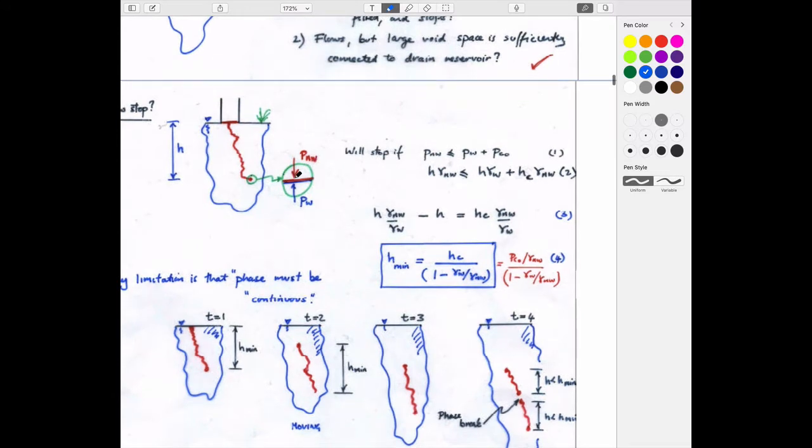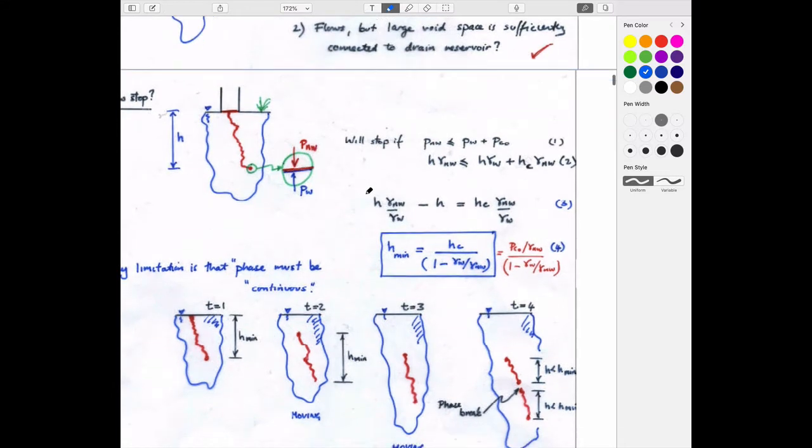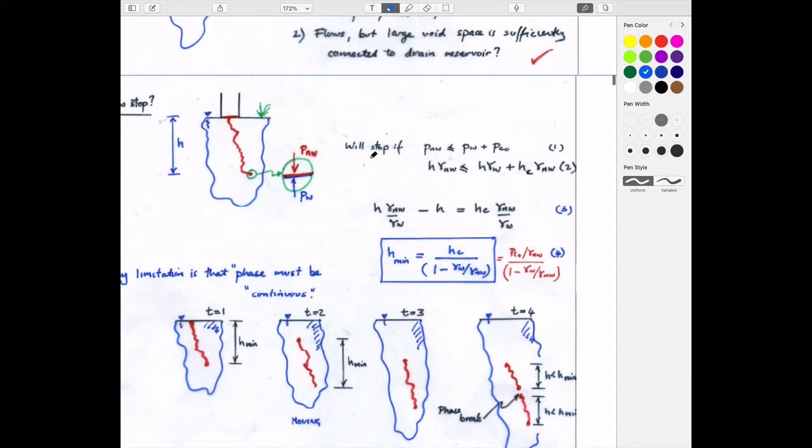And so the force balance at this place is equal to the red fluid pressure acting at this point, which is this, and the blue fluid pressure acting at this point here, which is just the depth of the blue fluid times the unit weight of water plus the entry pressure.